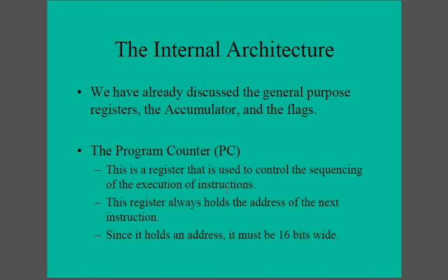That means the current instruction, for example, you are executing the move A instruction right now, so the program counter will store the address of the memory that stores that move instruction. That's why this register is used to control the sequencing. When you fetch another instruction, the program counter will be updated. It will be incremented by 1 to point to the second instruction from the code that you wrote.